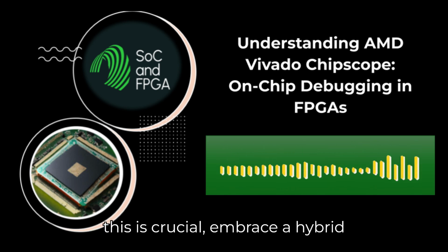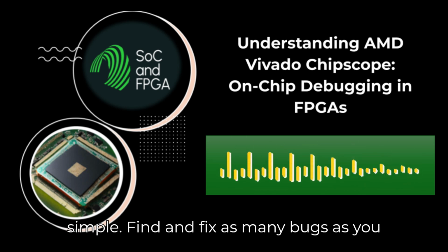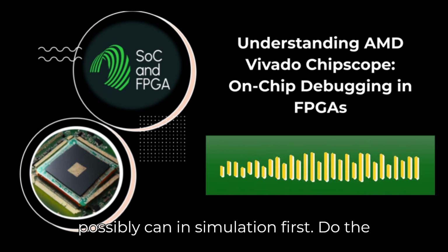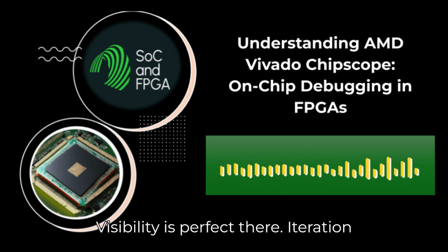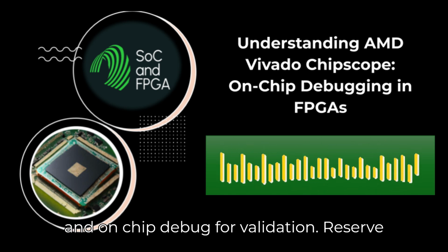First, and this is crucial, embrace a hybrid verification strategy. The golden rule is simple. Find and fix as many bugs as you possibly can in simulation first. Do the easy stuff in sim. Exactly. Visibility is perfect there. Iteration cycles are much faster. Use Chipscope and on-chip debug for validation.